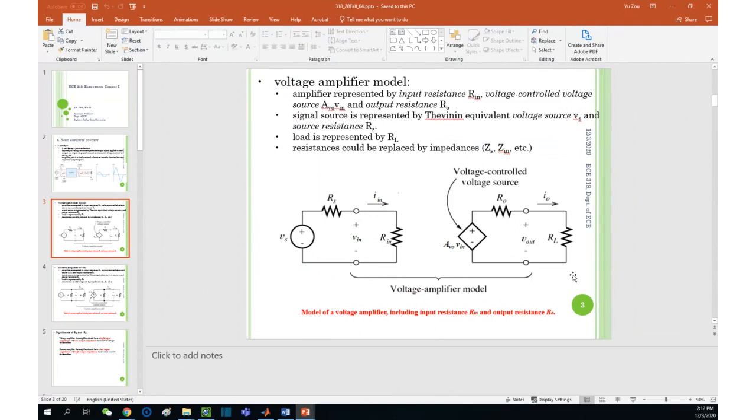Not a surprise. So when we attach the emitter follower to it with the load, should we expect to see numbers that are close to the 6 to 10 range? Correct. However, if you're not attaching the common collector output stage, you are directly feeding that 200 no load gain onto the 10 ohm load.